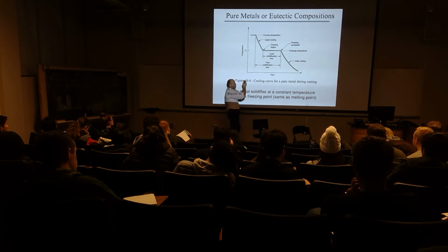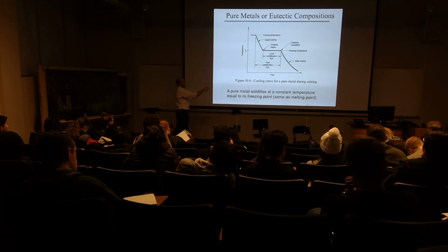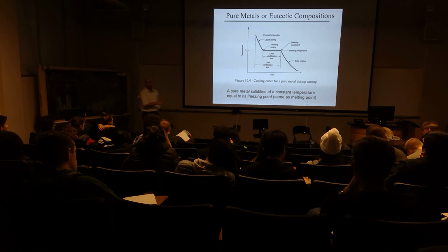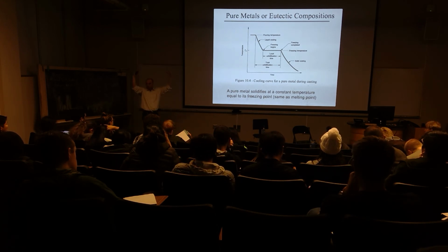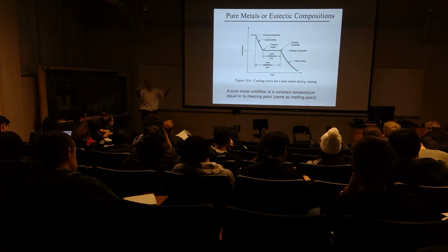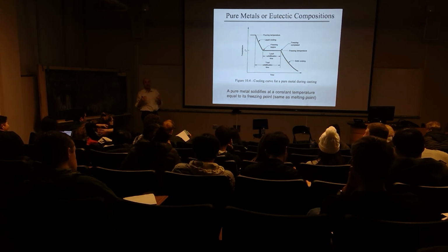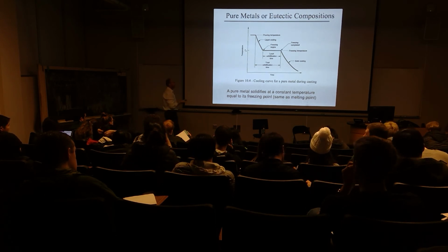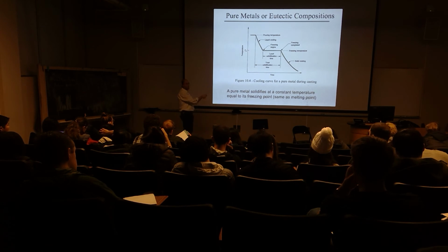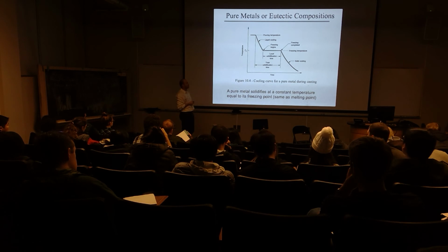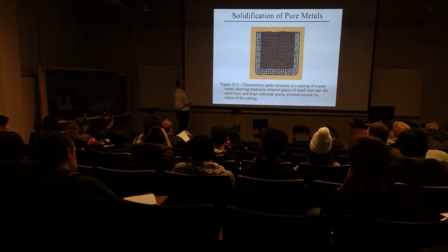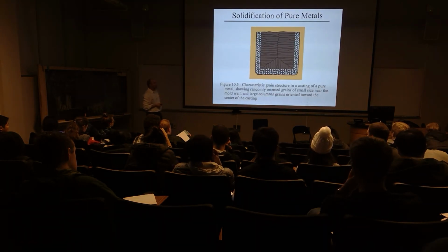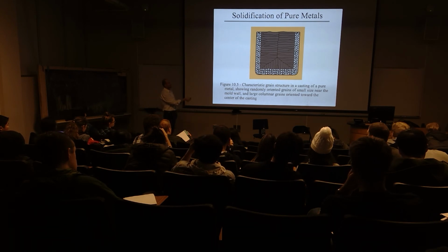But also we do that because all of this is heat that's conducted into the mold wall, which brings the mold wall temperature up and then keeps the remainder of the conduction process at a slower rate. So you can end up having less heat conducted from your metal because the mold was heated up during that process and now can't conduct that heat as efficiently. Okay? So let's look at a bond metal that was introduced within